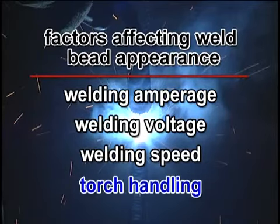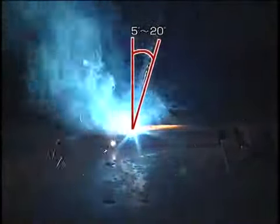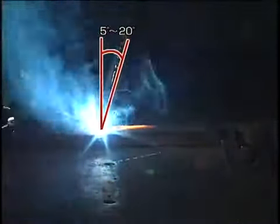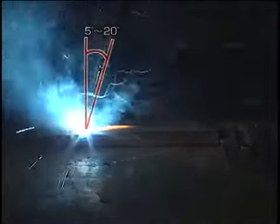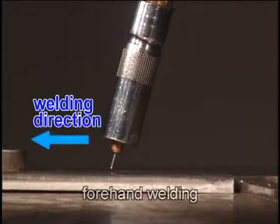Next, we will explain the effect of torch handling and how it changes the shape of the welding bead. The welding torch can be angled 5 to 20 degrees in the travel direction when welding. When the torch is angled in the travel direction as shown, it is called the forehand or push welding method.